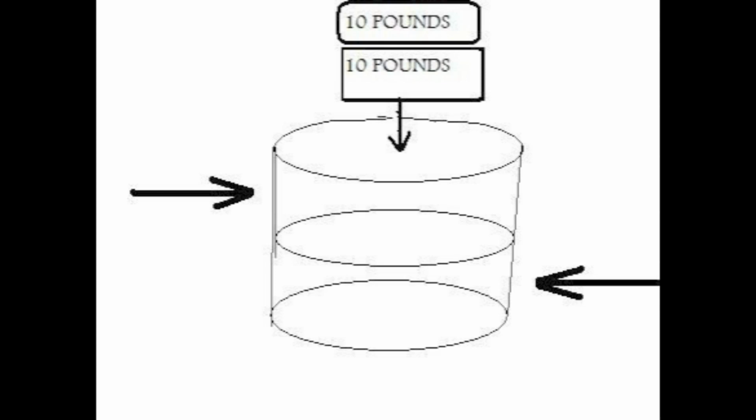The reason for this is because higher axial loads will compress the inner grains of the soil so that it is more difficult to move them horizontally, thus producing a higher ultimate shear stress. Now if we keep adding weights, the ultimate shear stress would theoretically continue linearly increasing. If we were to plot the first axial stress and shear stress corresponding to the 10-pound load, and the second axial and shear stress corresponding to the 20-pound load, a linear connection can be made between points.